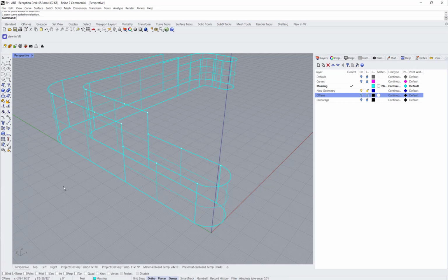We can illustrate that line by connecting the second control point to the end control point, and then by using the command set point, we can select the second control point and the end control point of our connecting curve to our target geometry, which is below.